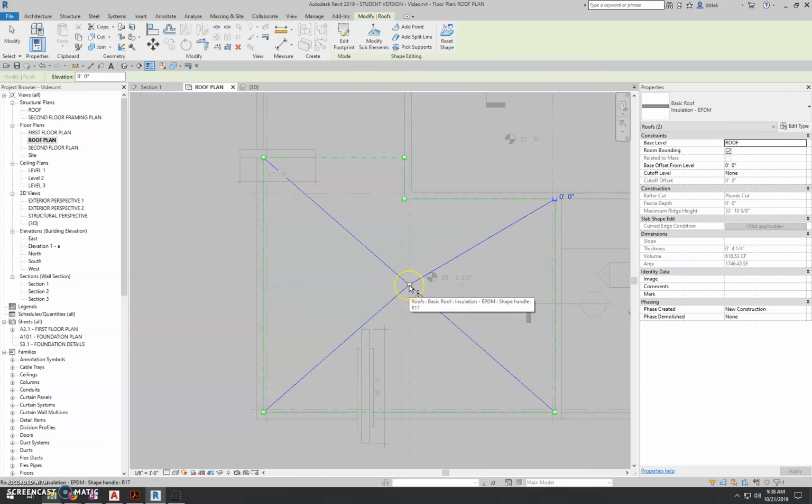So that would be like the regular roof, 4 inches of insulation with that quarter inch of EPDM on top. So all we have to do is change that from 0 to be 6 inches. So we're going to go around here. You have to click on the dot and then click on the elevation to edit it.